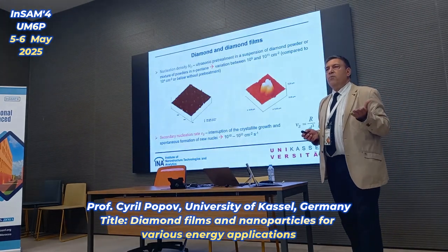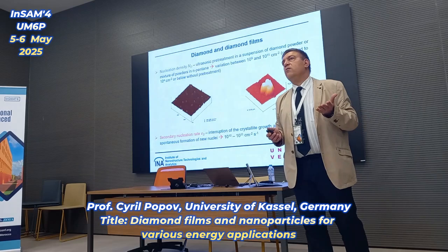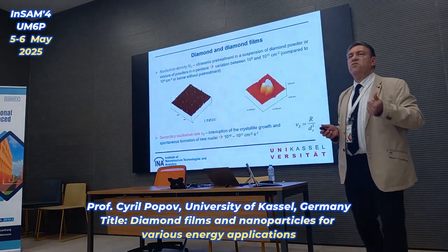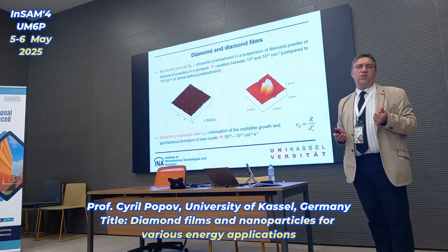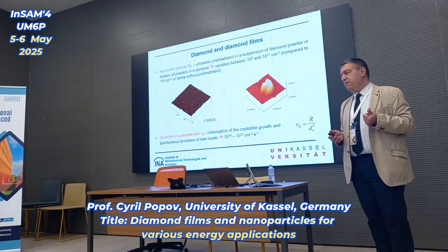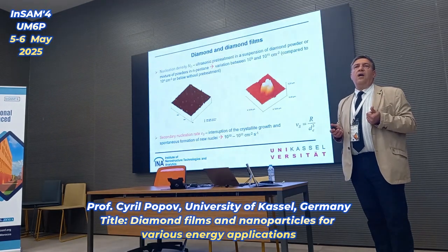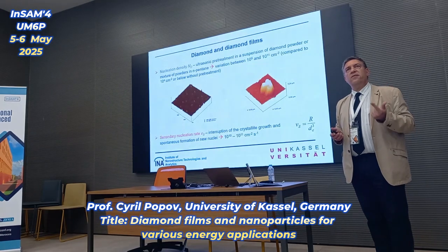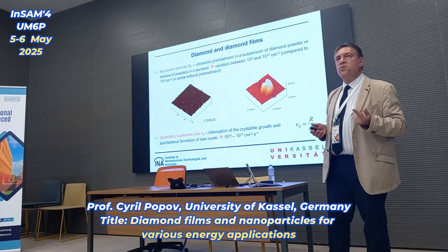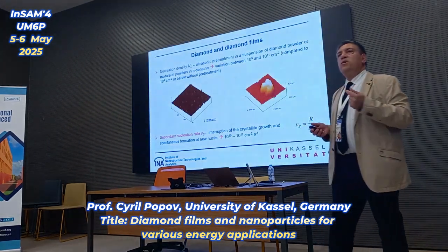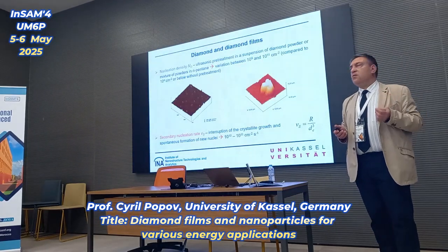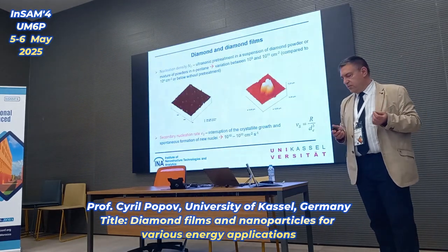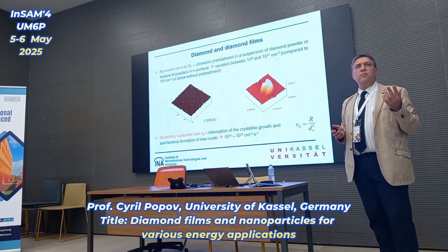You can deposit diamond on many materials, however, not on all. The first limit is the temperature that the material has to survive. And the second is that you have to pretreat the substrate to introduce the nuclei, which will induce the growth of a closed film. Let's take, for example, silicon.